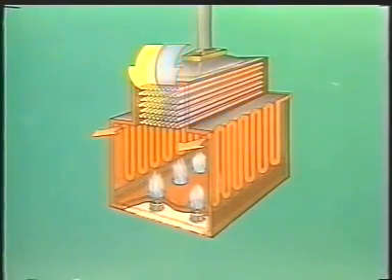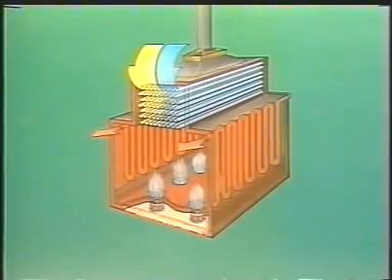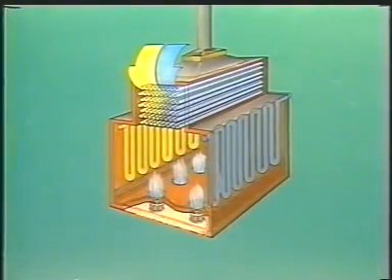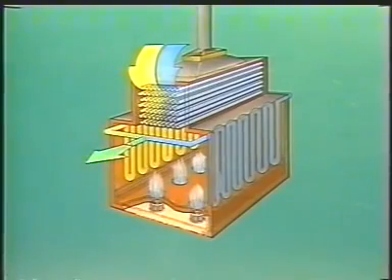The tubes which carry the process flow are generally divided into passes or coils. If the passes are balanced properly, each pass receives the same amount of process flow and absorbs the same amount of heat. After the process flow is circulated through the passes, it is rejoined at the outlet.